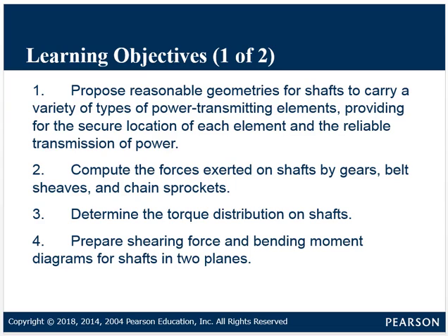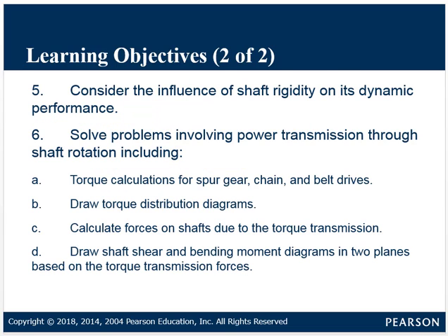Number 4 is to prepare shearing force and bending moment diagrams for the shafts, and these will typically be in 2 planes, so there will be 2 shear and bending moment diagrams per problem. Number 5, consider the influence of shaft rigidity on its dynamic performance.